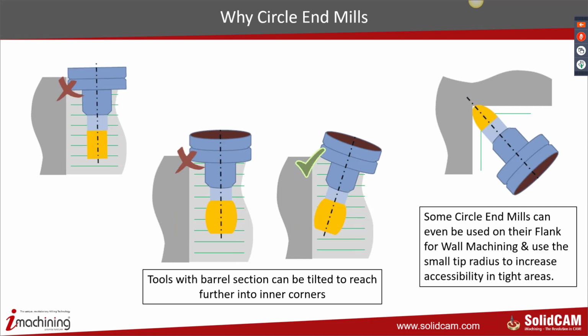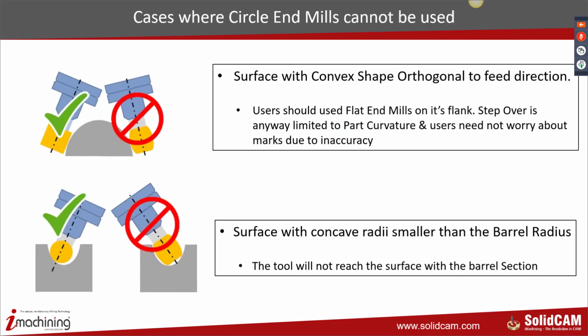Some of the barrel tools, like oval form tools, have got dual radius, one radius, and one on the flank that is a pretty large radius. The one on the tip is more radius, for fillet on the side wall or on the bottom. So the oval form kind of tools have got dual uses. They can either be used to machine the flank of the surface, or you can use the tip of the tool to machine fillets and other areas you cannot get in. So, dual use.